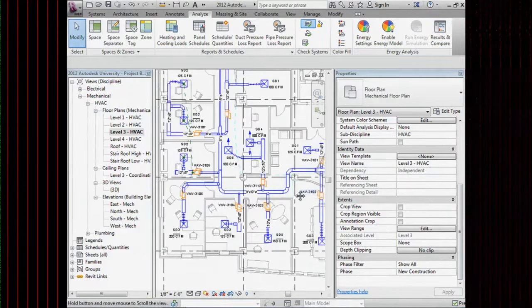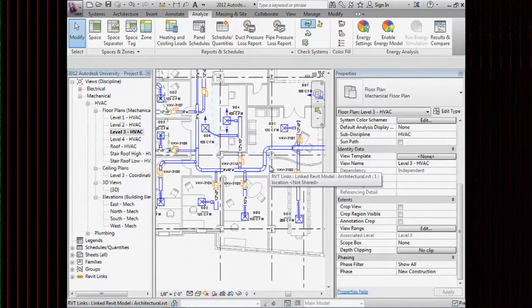All right. When I first got into it, I think the section was turned off. Section markers? Yes, we went in and had to go none for it to work. Section markers weren't turned on in VG. They were turned off by default. Yeah, we went through and extensively customized all the view templates for our projects, because you never know what you're going to get out of the box.